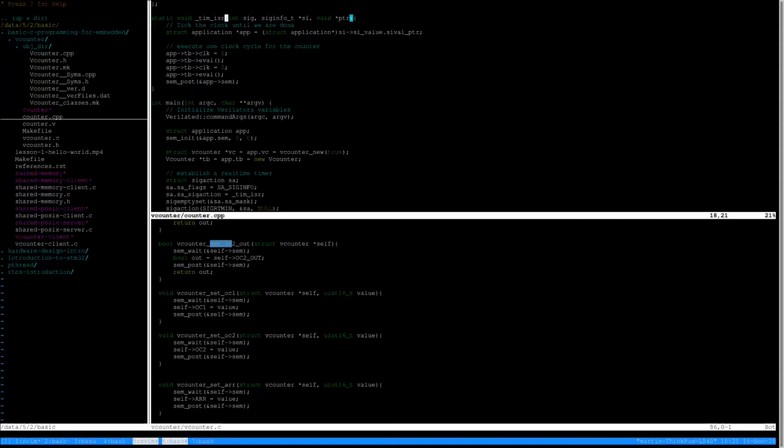When I have a timer that is an interval timer, the timer will simply continue and it will fire at regular intervals. So it's a lot better. It's a lot more precise, and every time the timer expires, the signal is going to be called. And then I will clock the hardware by toggling the clock line to 1, and then evaluating the hardware, and then toggling clock back to 0 and evaluating again. And the other registers of the hardware are going to be synchronized separately.